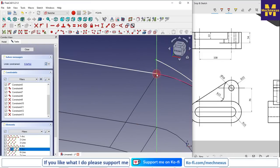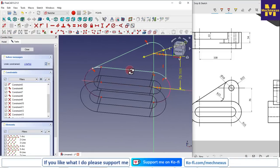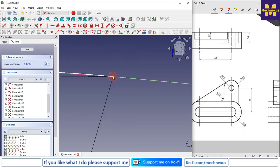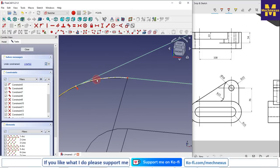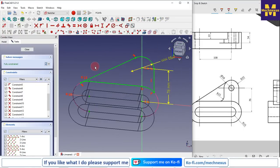I will select this point and this point, click on merge, then select this point and this point, say merge. So here this is constrained, and now here, okay, so here this arc is not fully constrained. So what we will do, we will select this one and this one, make it equal. So our profile is closed.